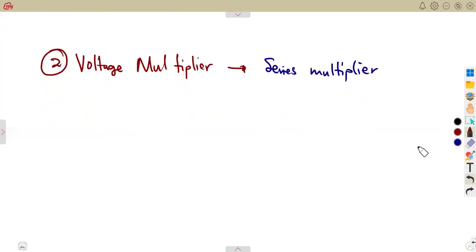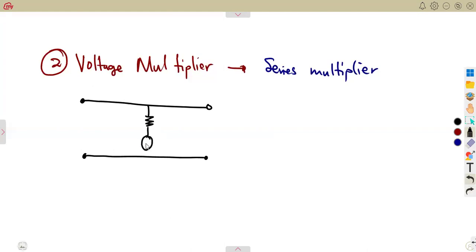So it's a connection that is simply in series. We're going to have something of this nature. Let's just see here, something like this. Then we have the resistance of the series multiplier. Remember, this is connected in series to the meter, which in this case is no longer in parallel. Remember, in the last part, they were parallel. This time, the resistance and the meter will be in series. So that is our meter in this case.